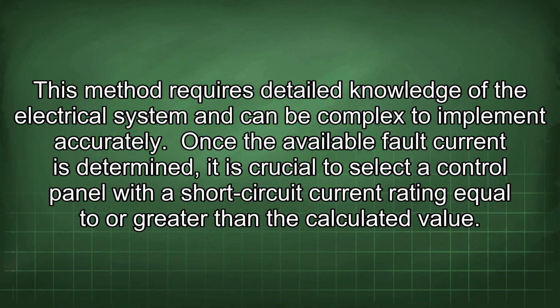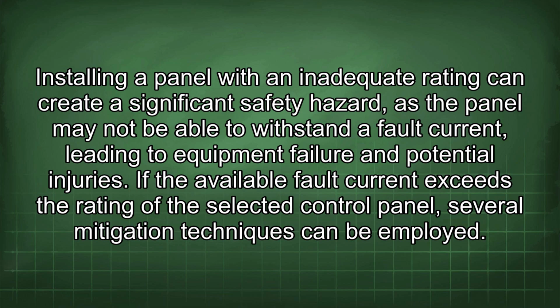Once the available fault current is determined, it is crucial to select a control panel with a short-circuit current rating equal to or greater than the calculated value. Installing a panel with an inadequate rating can create a significant safety hazard, as the panel may not be able to withstand a fault current, leading to equipment failure and potential injuries.